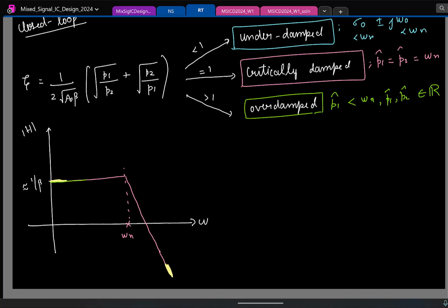So the lower frequency pole will occur before this or after this? I know the lower frequency pole is before omega n. So it's going to start to drop, let's say somewhere here. And what will be the slope? Minus 20. Okay. And remember that at very high frequencies, I should still be following this line. So again, the second pole should hopefully lie here.